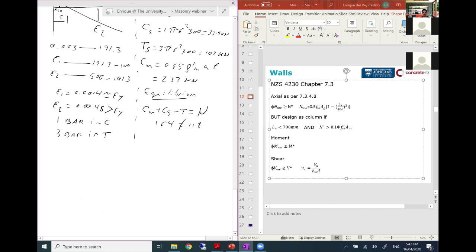We are going to estimate it, or we are going to assume. Now, obviously, I've done this a couple of times until I got the right answer. I'm not going to do 3 or 5% here, but if I use A as 135 millimeters, C at 158.8 millimeters, then my compression from the concrete is equal to 192.8.